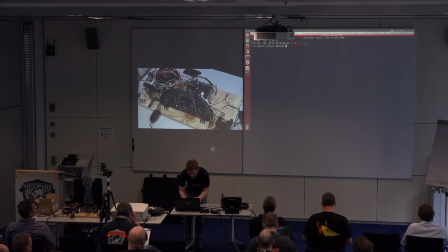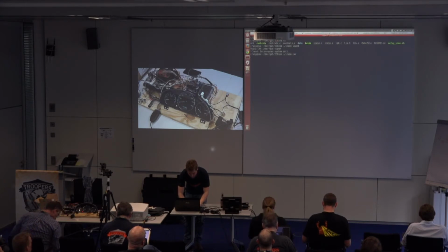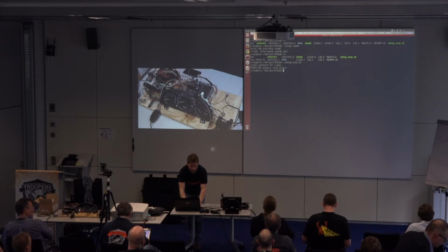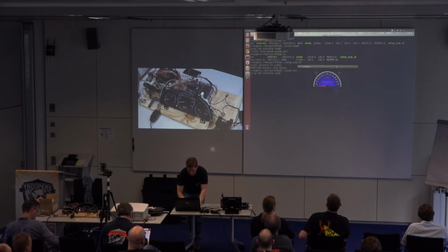Now IC sim, the way this works again is you have to have multiple screens running. You have one for your simulator. If you don't have CAN set up, there's a shell script here for your virtual CAN. That's the other really nice feature of SocketCAN: I think I already have it set up, you don't really need a CAN to play along. You just need Linux, and it can do virtual CAN buses. So we're just going to say the IC sim's on vcan0. All right.